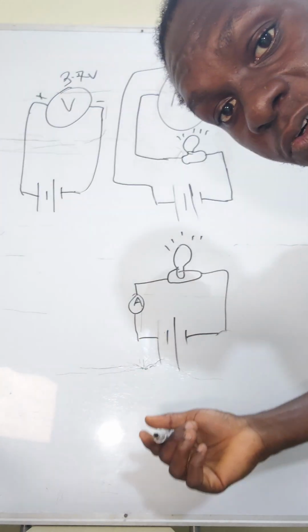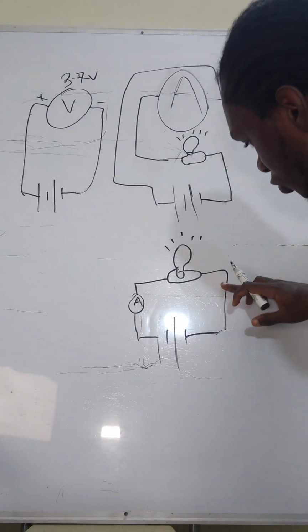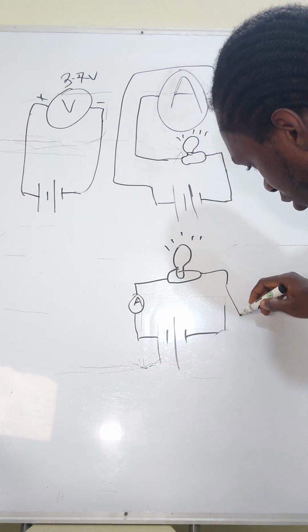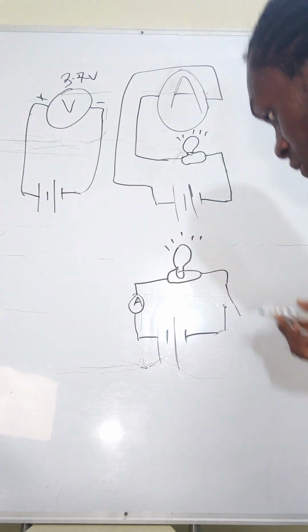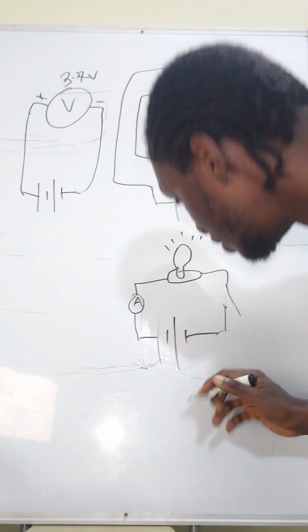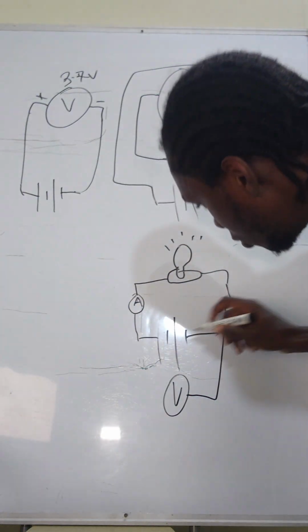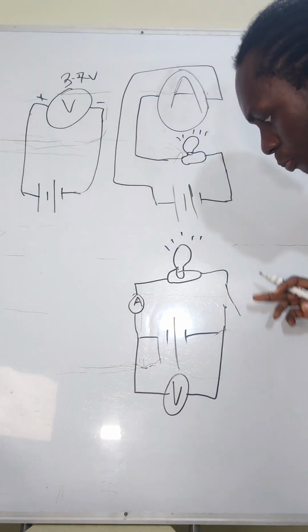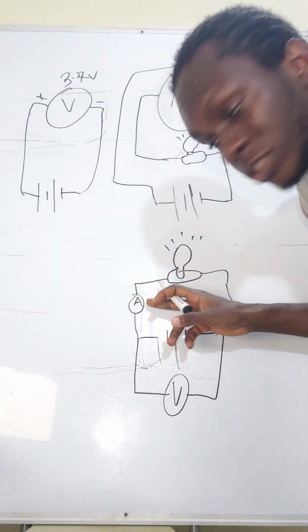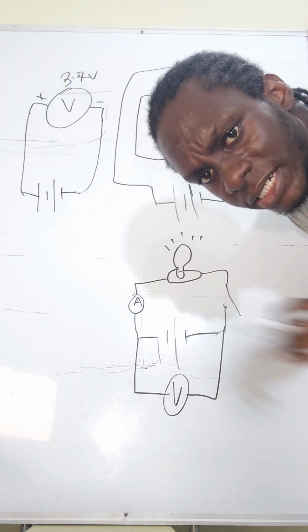If you want to check the voltage, maybe you want to see the voltage drop when you put this guy on, which means you are going to introduce a switch, so you could put it on and off. So we'll have a switch here. So this could go off and on. And we also want to see the voltage, right? So we'll have our voltmeter over here. Our voltmeter will now go in parallel with the power source. So when this is open, there is no current flowing, so this will be 0. This will be reading the voltage of the battery.